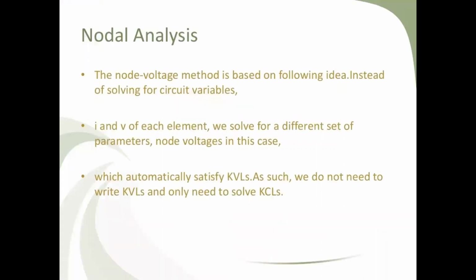The node voltage method is based on the following idea. Instead of solving for circuit variables I and V of each element, we solve for a different set of parameters, node voltages in this case, which automatically satisfy KVLs. As such, we don't need to write the KVLs, which is Kirchhoff voltage laws, and only need to solve KCLs, Kirchhoff current laws.